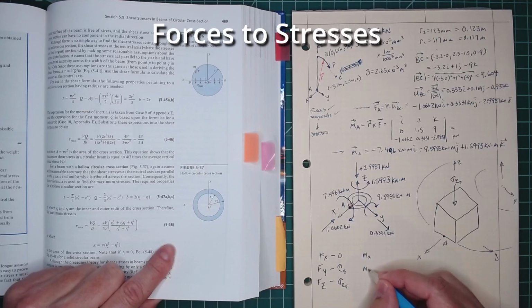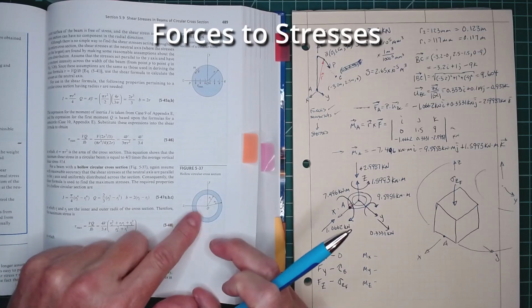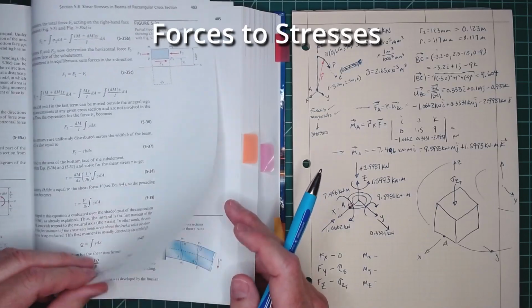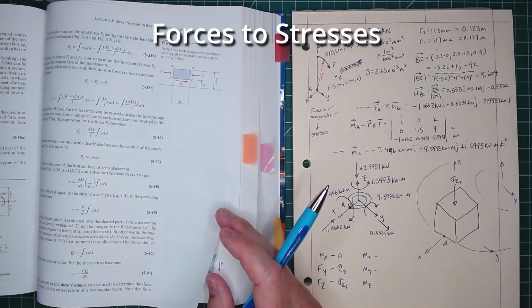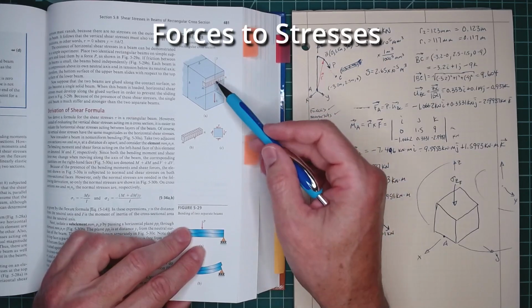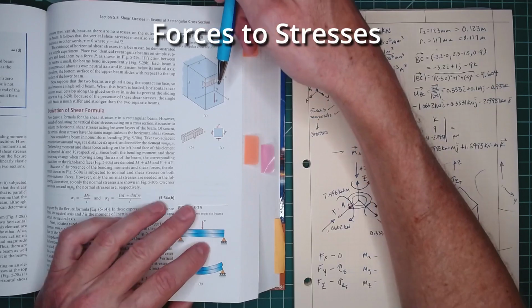Now we also have our moments. Moment X, moment Y, moment Z. Oh, and before we get to our moments, where is this shear acting? Well, if we take a look at our shear stresses, we need to go back to our beams, our cross sections. It shows it in the book, how this shear force is going. So the shear force on this cross section is in the downward direction.